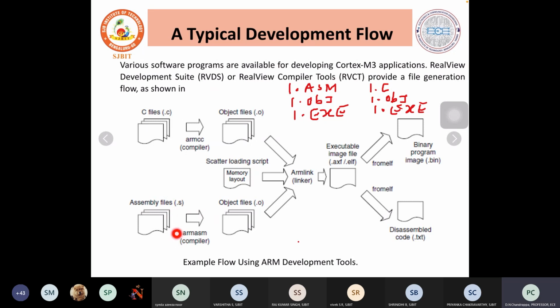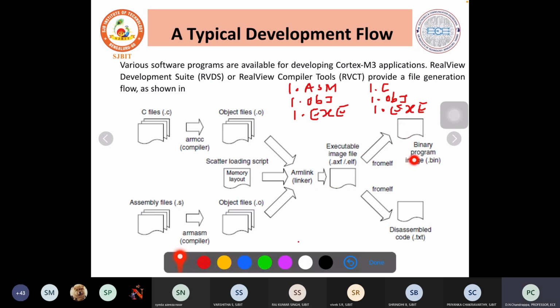Okay, so here this is the .asm file. Convert it into the .object files. Please look into this object file. Once compiled using ARM-ASM, it goes to the linker using ARM link, and then converts that object file into the binary files or the .exe files.